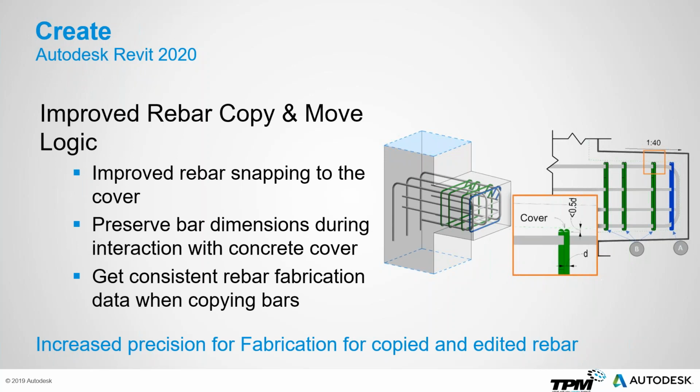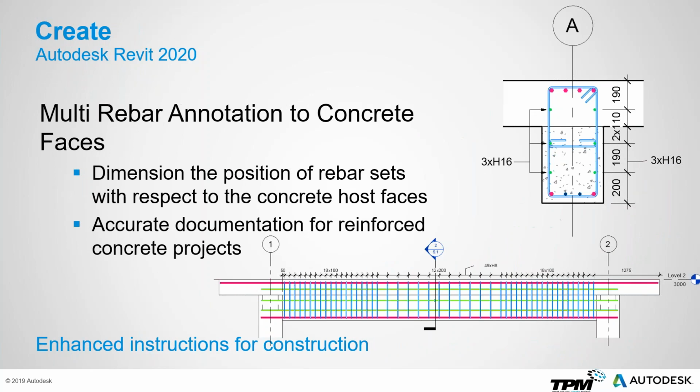Again, pretty much tied to somebody who is going to be doing fabrication or prefabrication with some of the rebar geometry that's out there. Along the same lines with rebar is the annotation and dimensioning. We now have the ability to work with these rebar sets and have annotation more easily accessed when working with rebar.